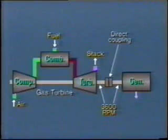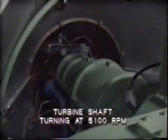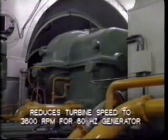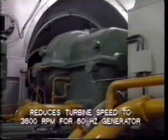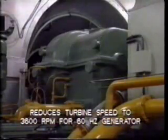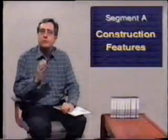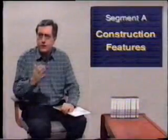Generally, in modern installations, the generator rotor is directly coupled to the turbine shaft. However, some turbines are designed to run at much higher speed, say 5,000 to 7,000 RPM. In this case, the generator is coupled through a gear drive in order to drive the generator rotor at the correct speed, that is 3,600 RPM for a 60 hertz generator. But what is it that determines the speed requirement? Well, we'll talk about this later.